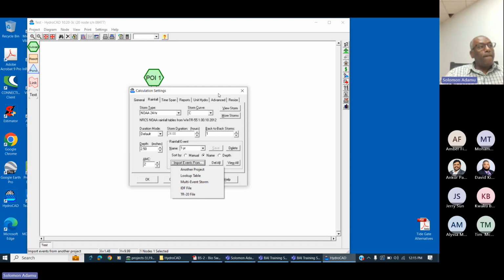Lately, we've been getting comments to use the NOAA rainfall intensity from the NOAA website. What we've been doing is downloading their intensity chart and then entering those values into your TR55. And then this program automatically pulls those things and assigns them there.